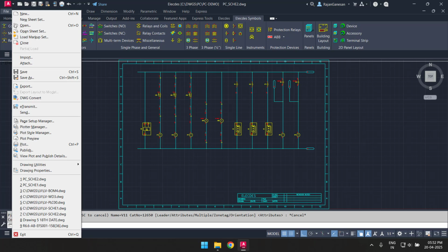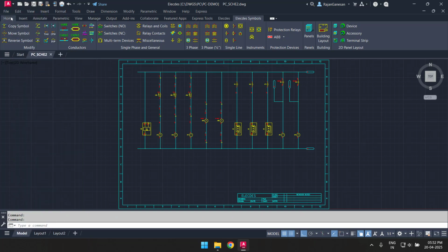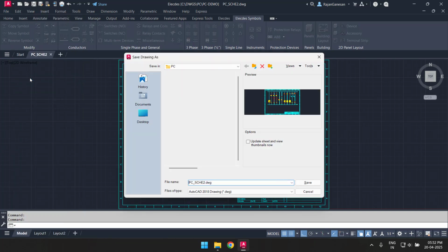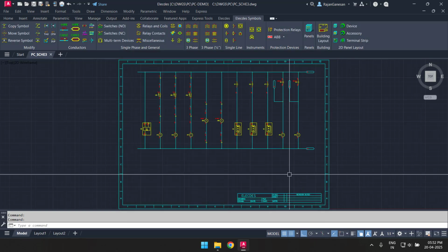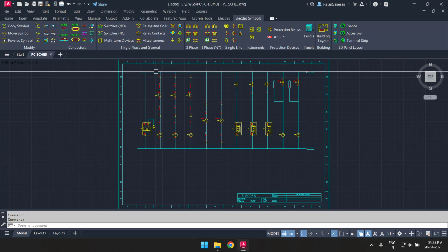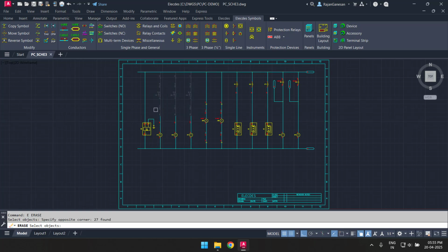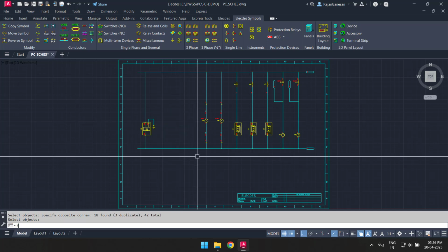Now that the DC circuit for my first protection control relay is completed, I'll save it. Next, I'll use Save As to make a third circuit. For the third circuit, which will be a DC circuit for the second PNC relay, I'll make a slightly simpler version of the circuit used for the first PNC relay. I'll quickly remove a few rungs from the ladder to simplify it, and then I'll use the Global Editor to correct any duplications I may have created.